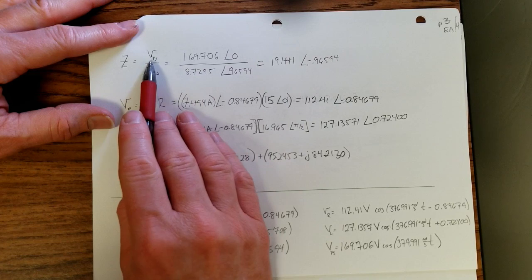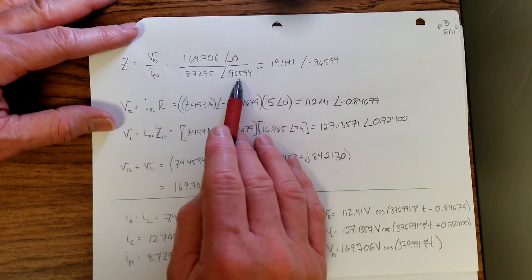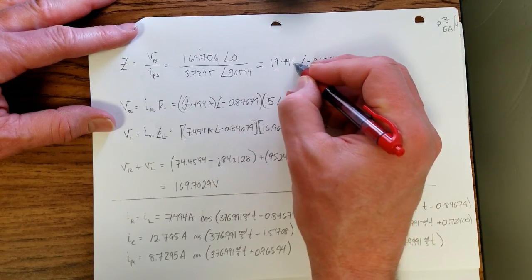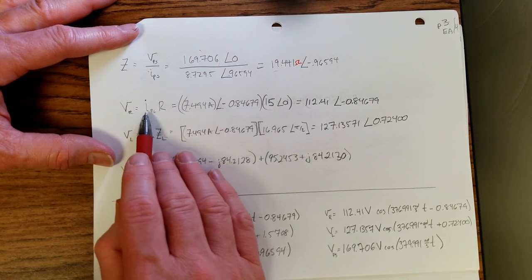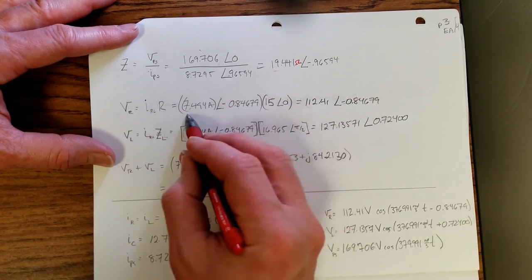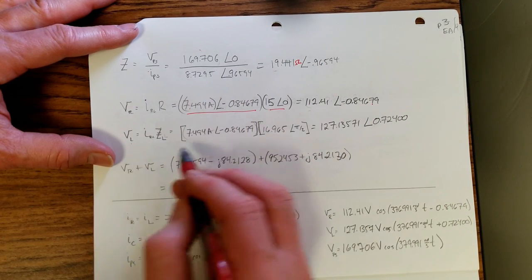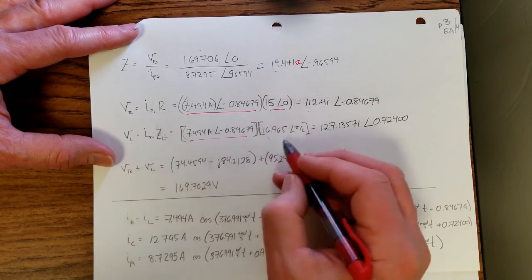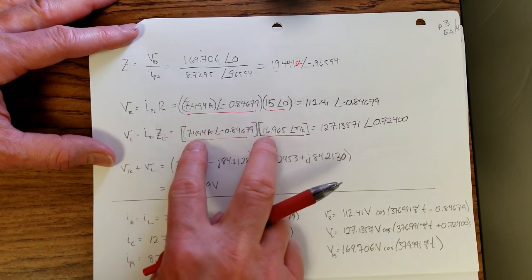So the total impedance is V sub PS over I sub PS, and so we just do a division of the magnitude of V sub PS over the current that we just found, and so we have our front part right here, and that should be ohms, and then the angle just subtract. So now we can find the voltage across each of them, and that's just voltage across the resistor is the current across it times the resistance. So I take my current, multiply times my resistance, and I get this. For V sub L, I take my current that I just found times my Z sub L, and again just adding those two to get this, and then multiplying the magnitudes to get that.